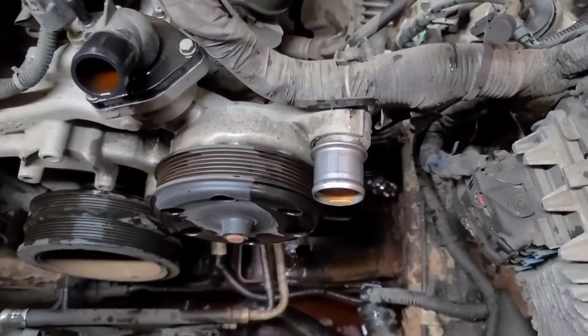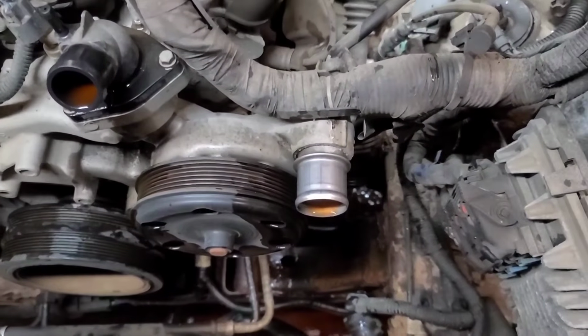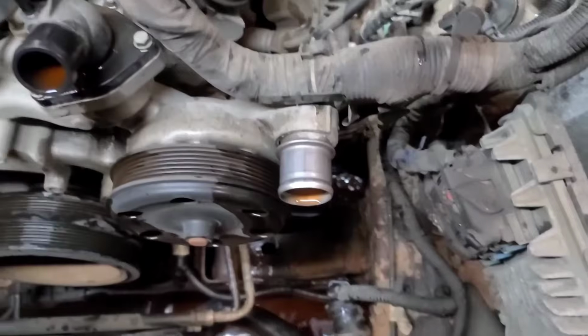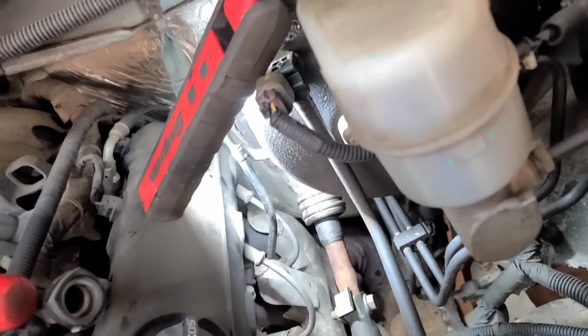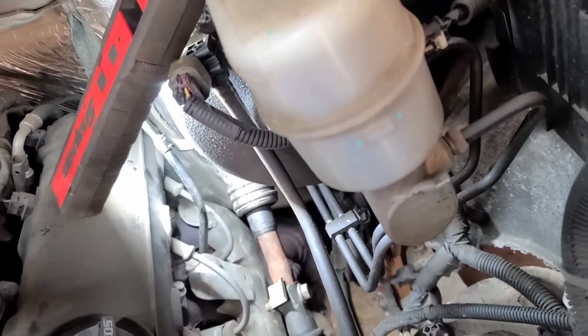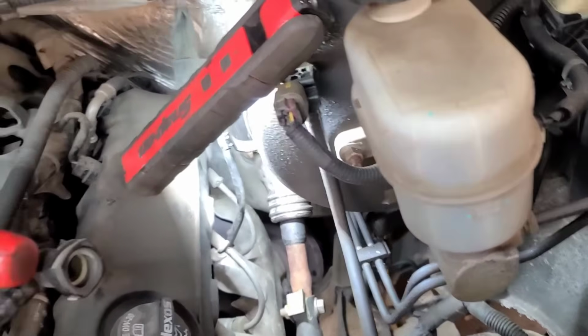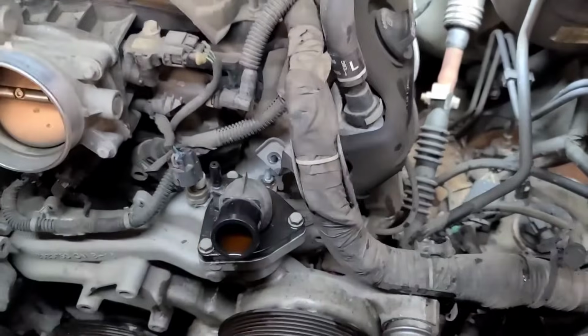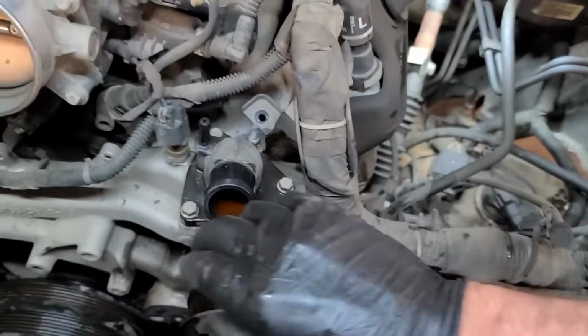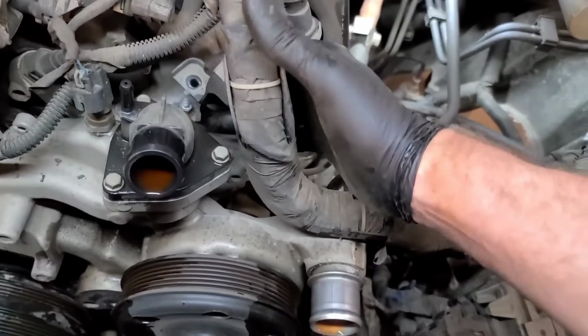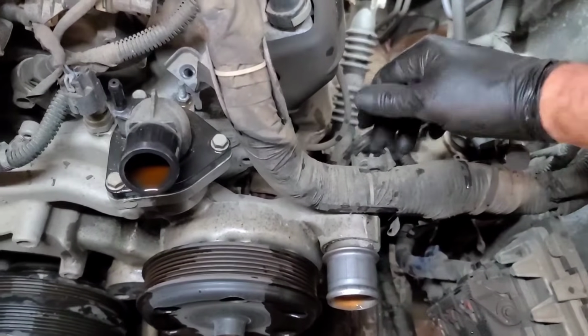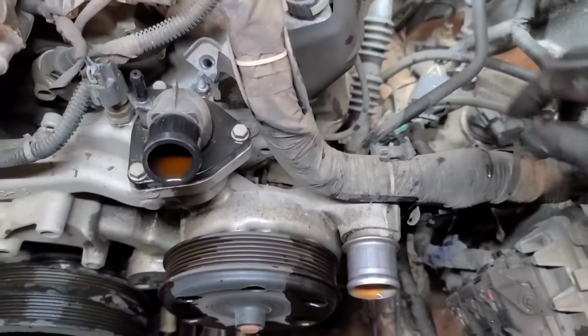So I just removed the upper and lower rad hoses and put the lower rad hose down towards the bottom of the rad to drain it into a big catch pan. Remove the little 6mm bolt that holds the dipstick back there to the head, and twist and wiggle it up and pull it out of the oil pan, and unclip the harness from the water pump assembly. Unbolt the bracket here, another bracket here, vacuum line to the brake booster there.